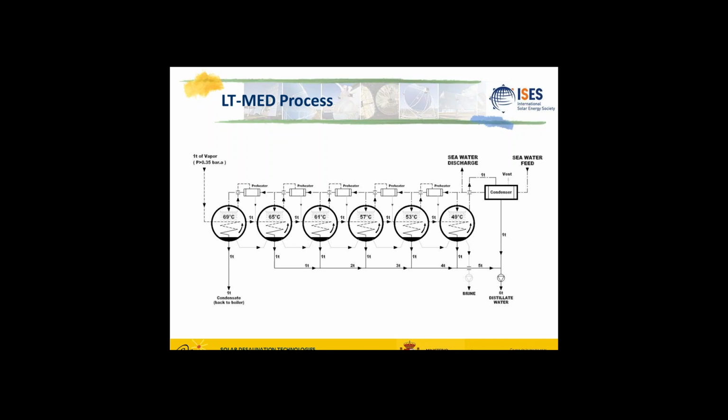Also, you know that the direct normal irradiance values that we have near the coast are not as high as those we have inland. And that means that we are going to require a larger surface area of collectors. And also other technological aspects, for example, the resistance of the solar collectors, because at the end they are metal and glass, and obviously you are going to have a very stressing ambient. For example, a saline ambient is not very good for solar devices.